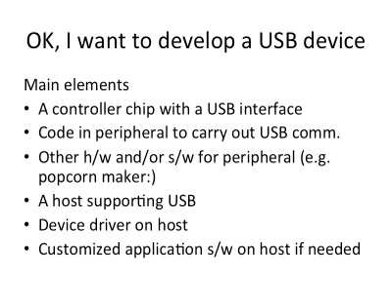So let's say we want to develop a USB device. Here are some of the main elements you need to have. You need a controller chip with a USB interface. Because of the complexity of the USB protocol, it's not feasible for you to design from scratch. You do not want to write the firmware of your microcontroller to handle all the possibilities of USB messages. Instead, you need a USB controller that's capable of doing this work.